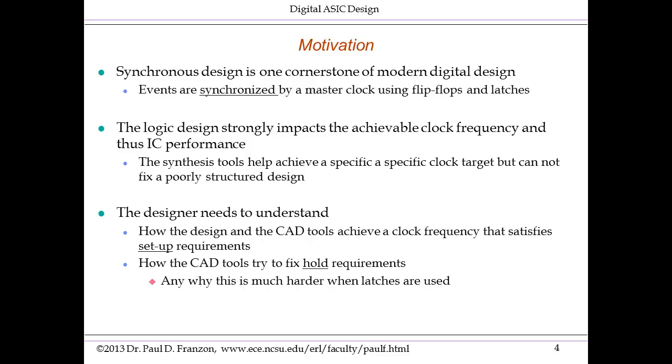More specifically, items are stored on those flip-flops and latches that are needed in the next clock period of the operation of the chip. Now, the logic design, the combinational logic between those flip-flops and latches, is what determines the clock frequency and thus the overall performance. Later, I'll show you how you can manipulate synthesis to actually get the clock period down. However, this is not a magic bullet. It can only do it to within the degree permitted by the designer. The structure of the design largely determines the clock period, not the proficiency of the synthesis tool.